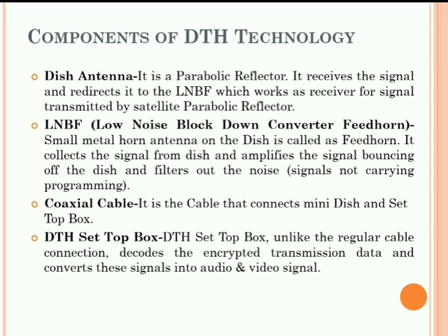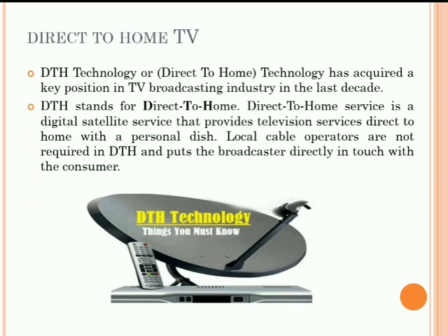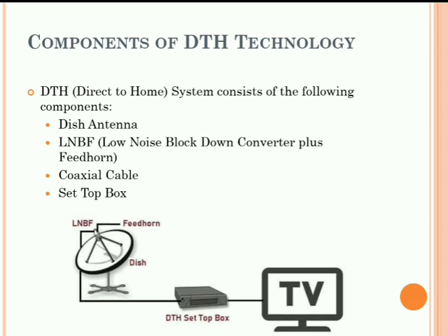What is LNBF? It is the low noise block down converter feed horn. The small metal horn antenna on the dish is called the feed horn. It collects the signal from the dish, amplifies the signal bouncing off the dish, and filters out the noise, that is, the signal not carrying the programming. You can see the LNBF in this diagram.